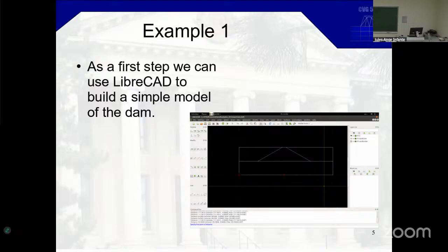So this one is definitely a tool that you should have. It lets you do 2D CAD, and only 2D, so it's not as powerful as AutoCAD, but its native format is DXF, which AutoCAD can open directly. So drawings that you make with this can be opened in AutoCAD, usually without a problem. But this little program has one advantage, which is that it has an export to image function.